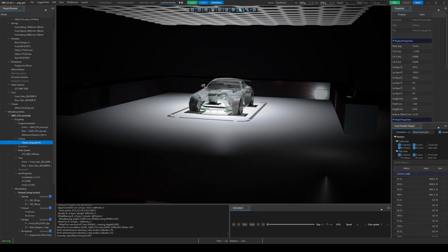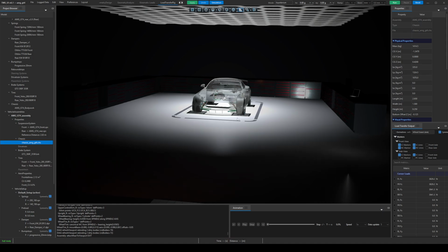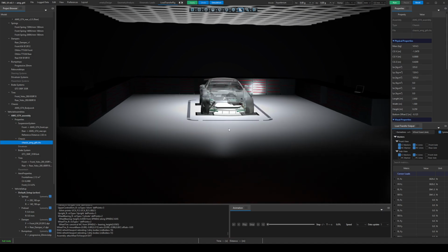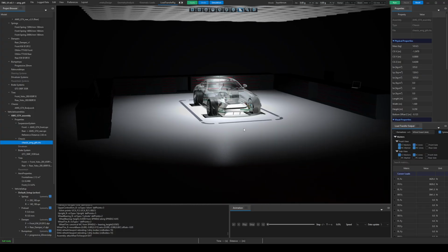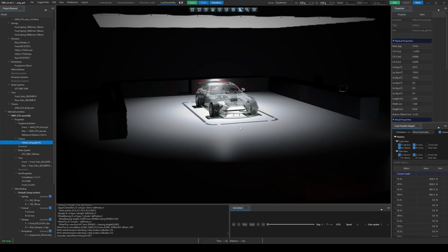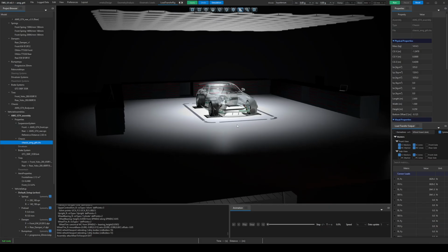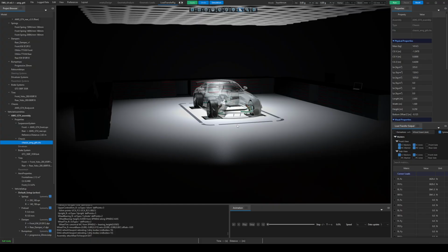The goal of this module is to help the user understand how setup parameters affect tire normal loads under dynamic conditions. That includes springs, anti-roll bars, dampers, ride heights, and suspension geometry changes. This is useful for both existing vehicles and new suspension designs. On existing cars, there may already be alternative pickup points available. Many transaxle gearboxes, for example, provide multiple control arm mounting positions. This module is meant to make those options easier to evaluate, with fewer guesses and fewer heroic assumptions.